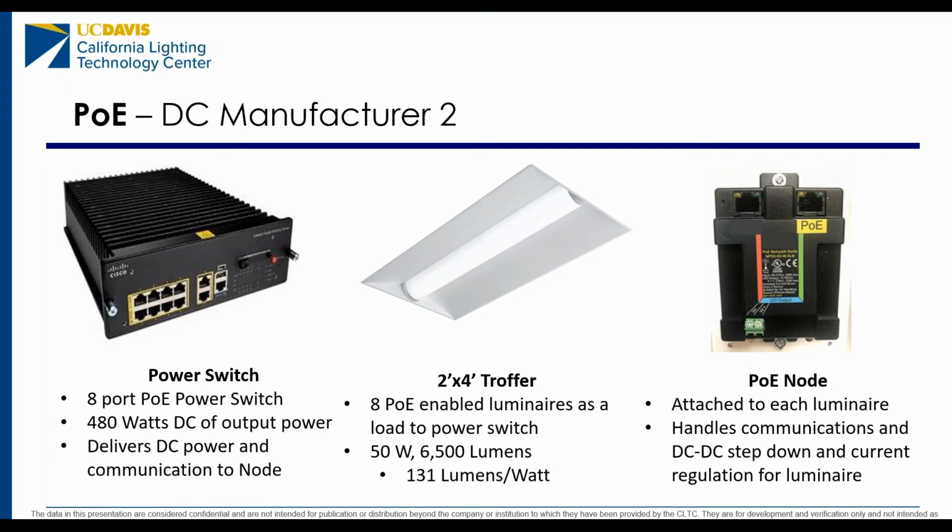And again, in order to load the power switch as much as possible, we bought the biggest 50-watt luminaire that they offered. And then finally, there's the PoE node, which is attached to each luminaire. Again, it handles the communication from the power switch, and then it gives regulated current and voltage to the luminaire as needed.